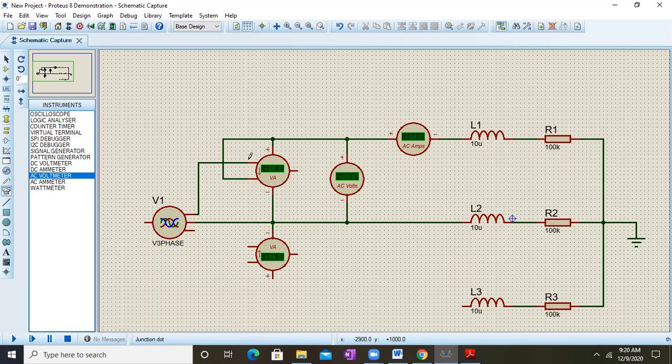Like this. Fine. And for the lower wattmeter also we have to make the connections. So over here we will connect it from here to here, and similarly the connections of the Y phase will be over here, and this current coil has to be in series. So here it is. So that's how the circuit will look. You can see carefully. Okay, so these are my connections.